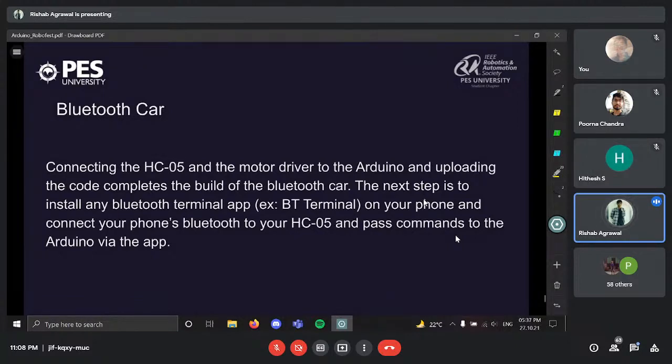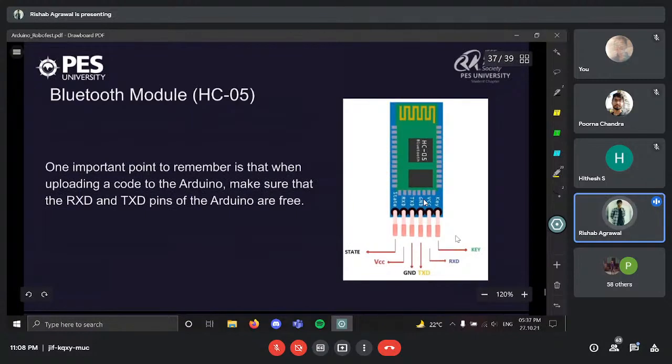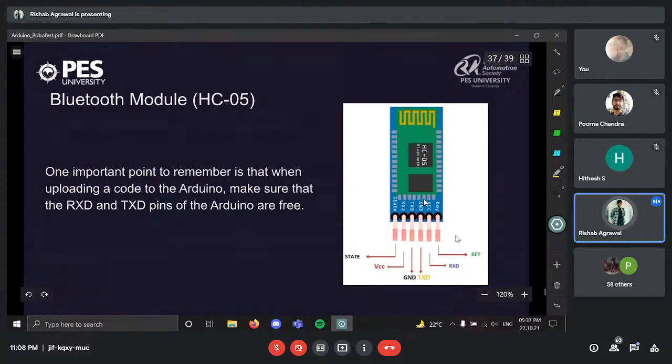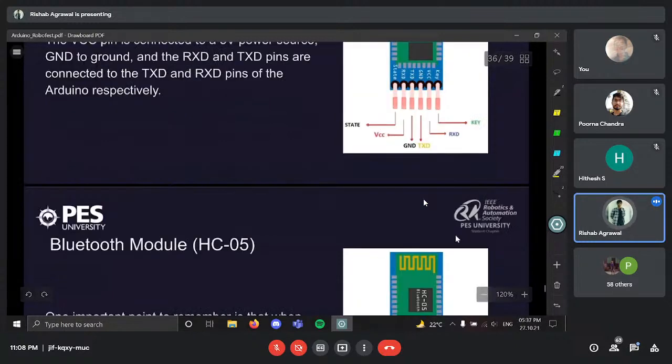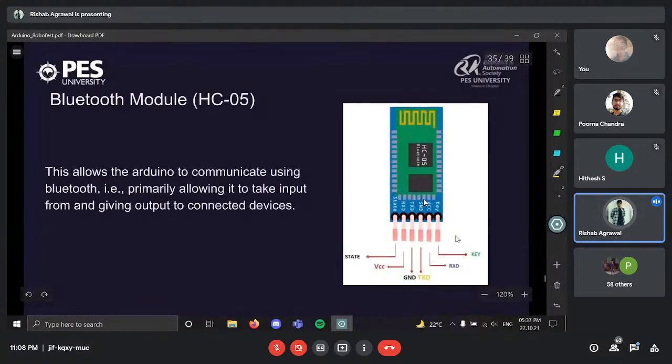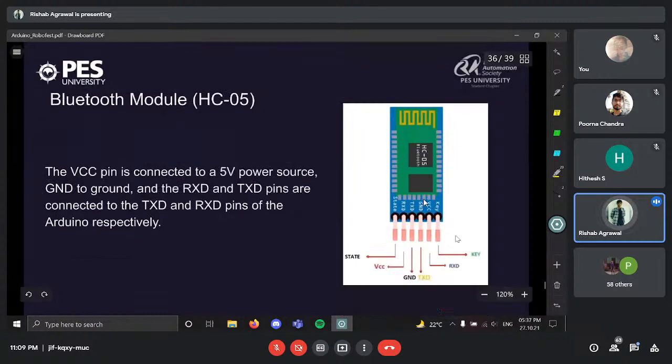But that's not very related to Arduino. You can search for sensors, and whenever you want to see how to use a sensor, all you need to do is probably just type the sensor name and pinout, and a pinout is basically a diagram like this one, for example, or this one. It helps you see all the pins, and then you can also search for the relevant codes and use them accordingly. I think one of the best things to do is use the standard methods of printing out the values to see what the sensor is giving out, if it's an ultrasonic sensor or an LDR or even an MPU 6050, like I said. As and when you're turning it, you can see what values it's printing, and accordingly you can decide what the actuators are supposed to do.